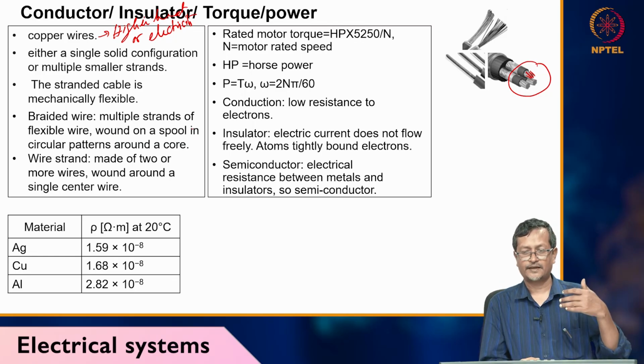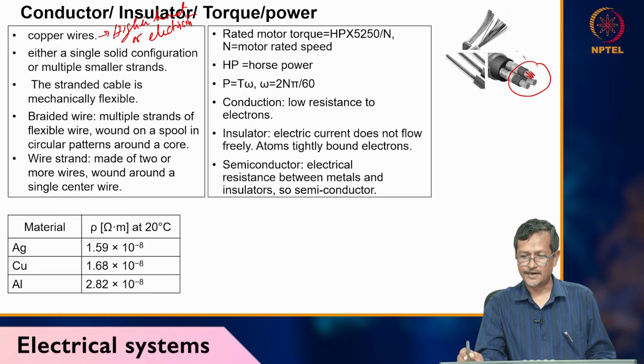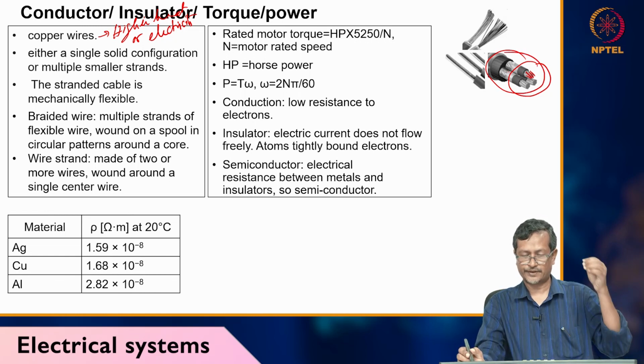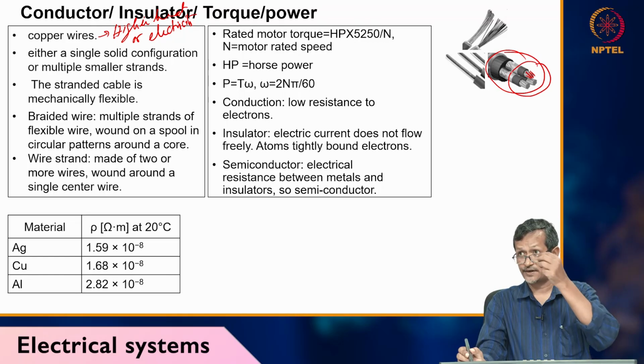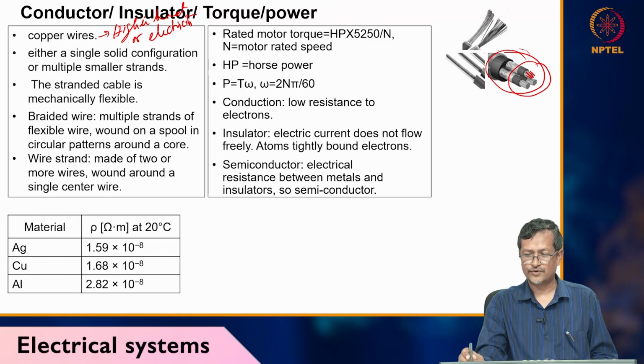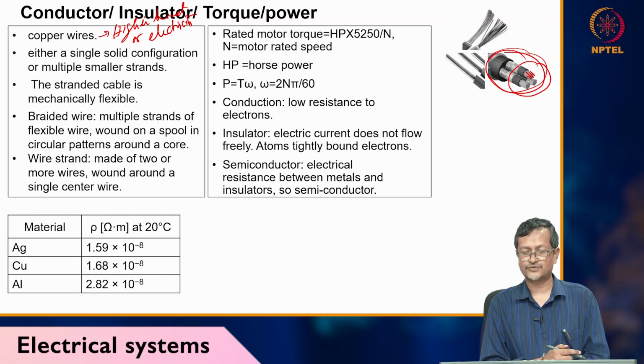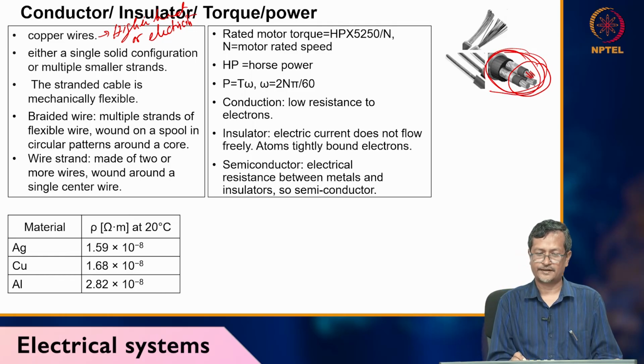So for higher amount of current if you are carrying, insulation is also very important, for example in marine application. In that case, multiple levels of insulation will be provided. But in normal application, let's say household application for electric bulb fixing, you do not need so strong a cable plus insulation level. But especially for marine and difficult areas where insulation failure may cause a severe issue, there you use heavy insulation and carry current.